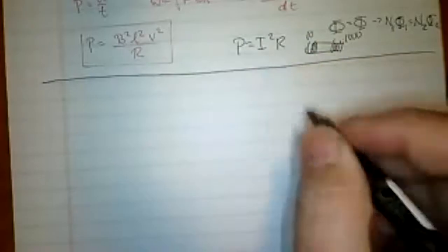What's happened now is you've increased the voltage from 10 volts to 1,000 volts, but you've decreased the current from whatever you had to that divided by 1,000. So by bumping that voltage to a higher voltage, you're decreasing the current by the same amount, and therefore you're getting rid of this loss of energy. So that's ultimately what won it out.